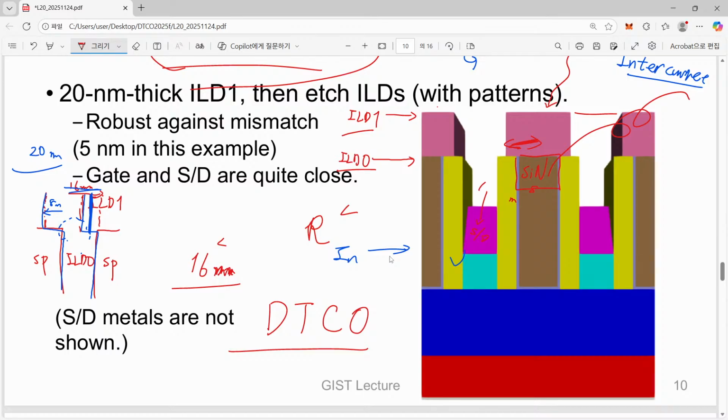But now the FEOL part is already much advanced, and we have spent a lot of effort on this FEOL part, and people think that maybe this MOL, the middle end of line, is the place where we can get some further advantages. So that's the main content of DTCO.